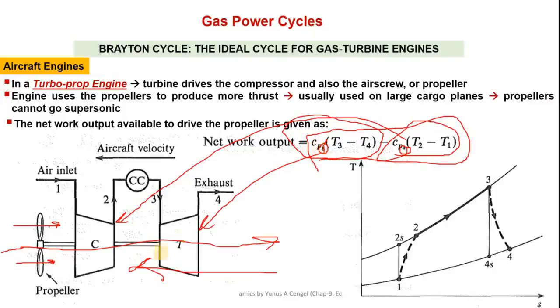That's why this Cp in this process will be a little different than the Cp in the compressor process at low temperature. That's why here it is written as Cpg, specific heat of burnt gases, and this is Cpa, specific heat of air at low temperature. It is also air but at much higher temperature, so Cpg could be different from Cpa.